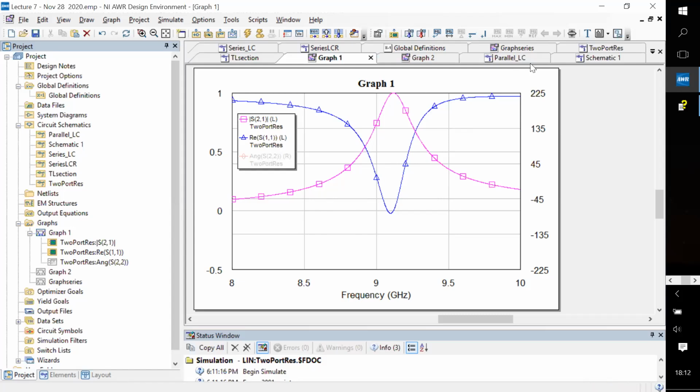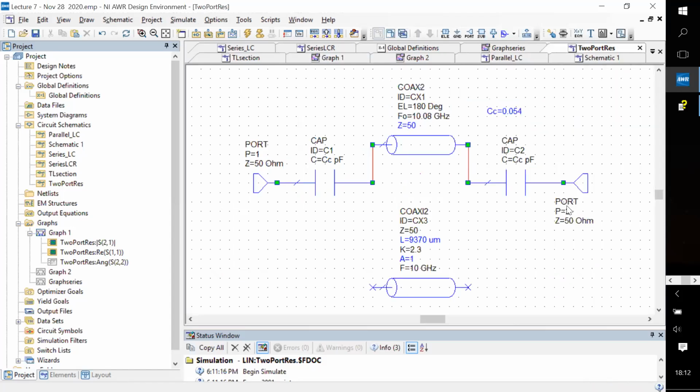And you have to keep in mind that when you have a symmetric system like this, the loss, the Q factor, is going to be determined by the losses from both sides. Both of them contribute to the loss. Even though it seems to look like at resonance the transmission is perfect, that is a misleading way of thinking about saying that, okay, maybe all the power is leaking out of here as well.